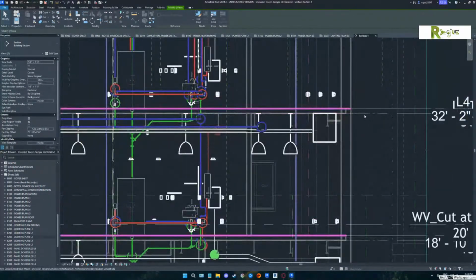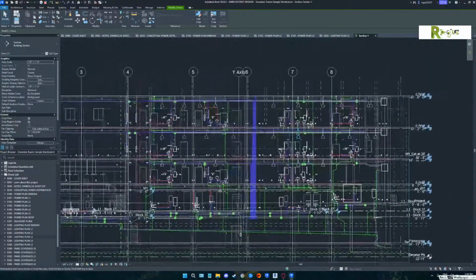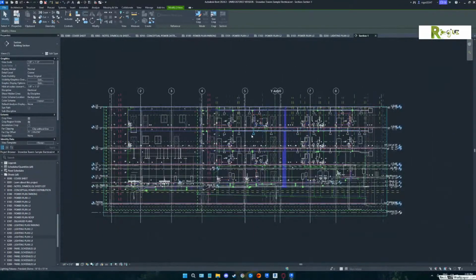Yep. Now, what most people don't understand, here's a shocker. A structural file level 1 should not typically be in the same place as the architectural file level 1, because the architectural level file for level 1 should be to the finished floor, where in structure they usually go to the top of the steel, so they usually go to the underside of the deck. You understand what I'm saying there?